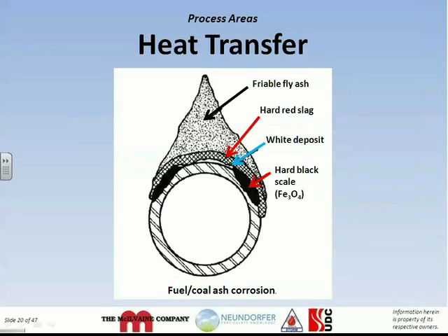Slagging causes plugging and poorly distributed heat transfer. Some tubes are much hotter than design, and some tubes are much cooler. Failures always occur at the extremes, not the average. This imbalance creates long-term overheat conditions in portions of a component. However, when we do a pressure part replacement, replacement of all the tubes is not normally necessary, but we do it because of the economies of scale. Many good tubes are scrapped and money is wasted due to premature replacement.